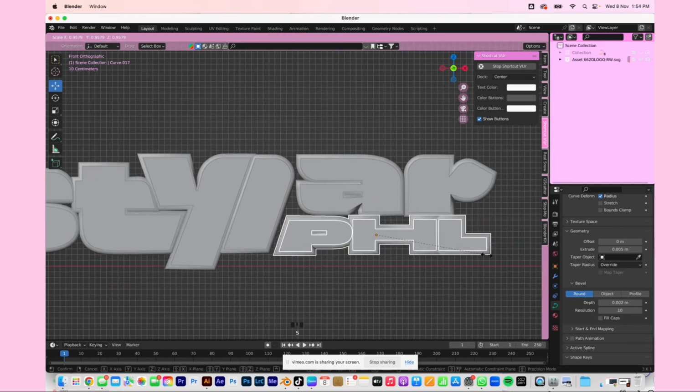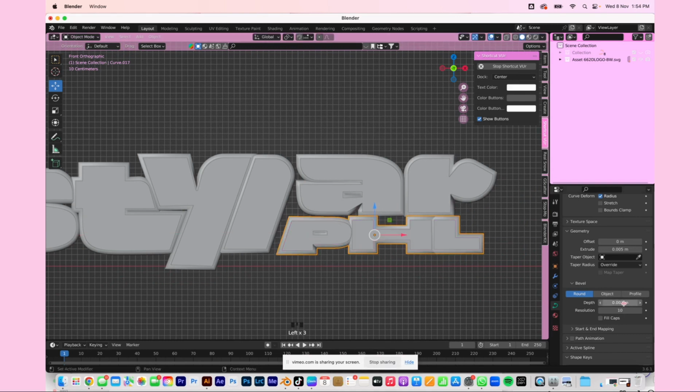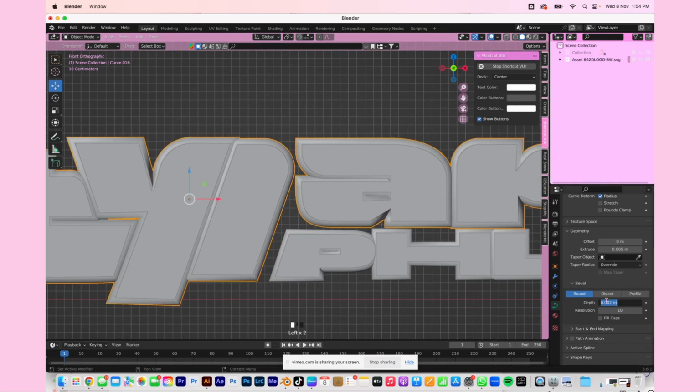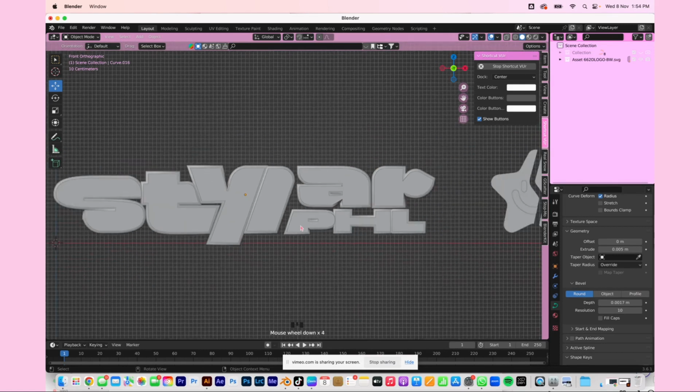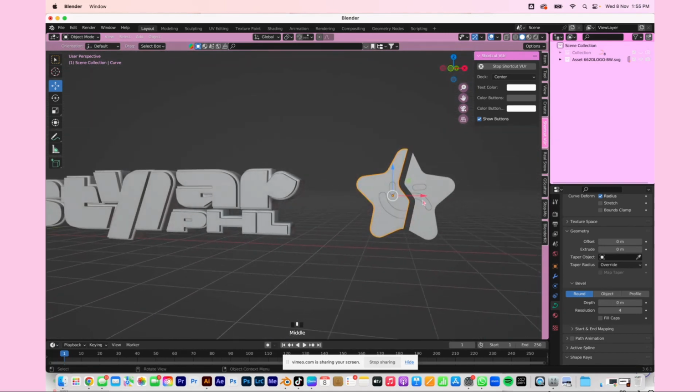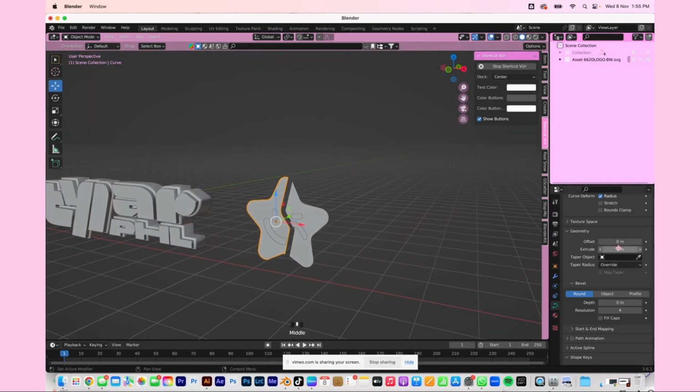I'm gonna decrease the size of this because it's touching too much, and I probably put this to 1/16, so it's a thinner outline. Same for this, I will do 1/17. All right, so that's done, and I'm gonna go ahead and do the star, and I'll extrude to 0.002, actually a little more. I'll go for 0.003.